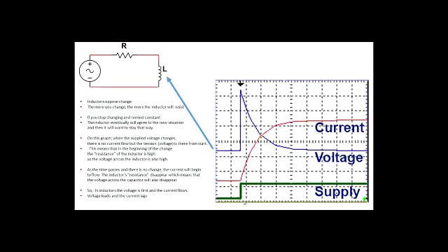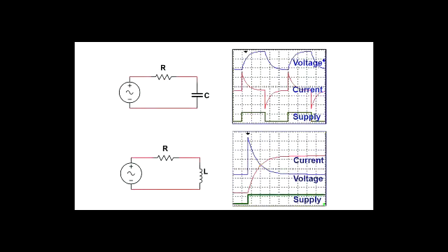In the coil, we have the voltage first and then the current flow. Now here's the side by side, or one under the other, just if you want to compare that. See that? In the capacitor, the current, here's the current, it flows first, and then the voltage. So current is first in the capacitor, and the voltage builds up later.